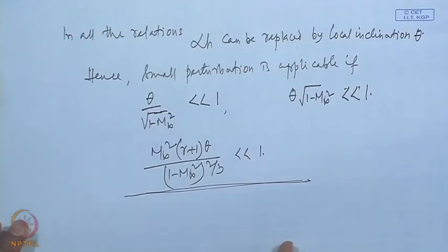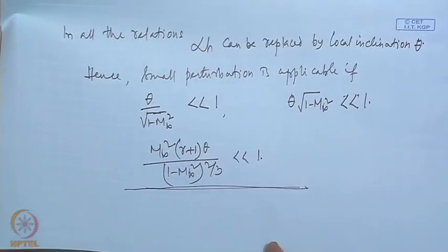In other words, the pressure will not be in phase with the wall, pressure will be in anti-phase with the wall, and consequently a drag force will be present, which we found in earlier cases also, that in a supersonic flow there is drag even in inviscid flow, which is due to the wave nature of the supersonic flow. So, we will be seeing that here also. However, we will consider that solution of supersonic flow past this wavy wall in our next lecture.